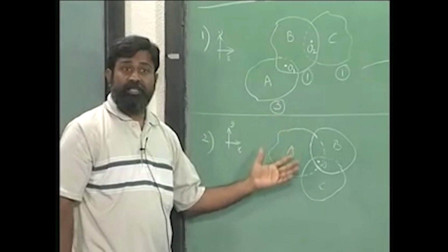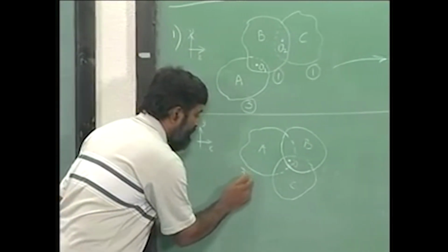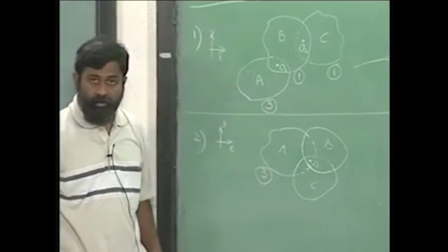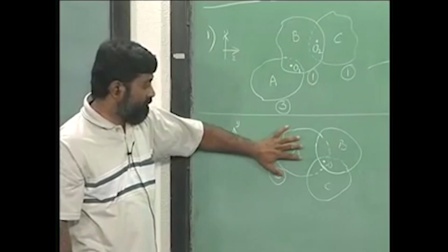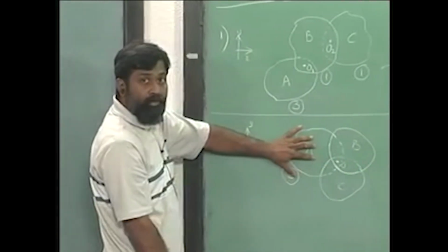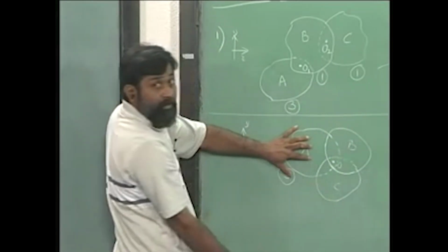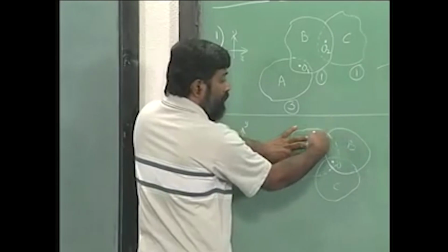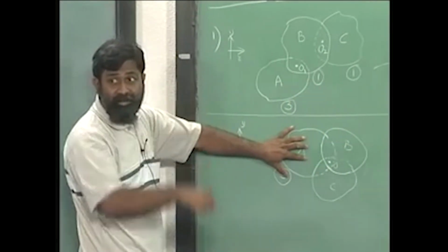So as we started earlier, if we look at this body A, this will have 3 degrees of freedom, no problem, and if I fix this body to the fixed frame of reference and ask the question how many ways can B move, B can move independent of any other body in one way, or in other words it is just the rotation possible.